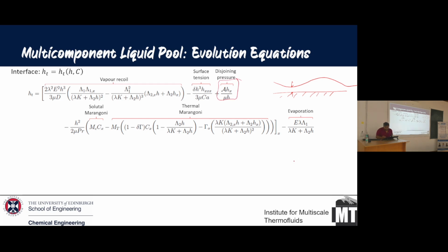So what does that disjoining pressure do? It can go as small as possible, but it is having some sort of a tolerance, and that is determined by the Hamaker constant. This is the point where it forms some kind of a precursor film. So this is also a modeling device to stop the simulation from going mad, but this also shows some level of dry out.